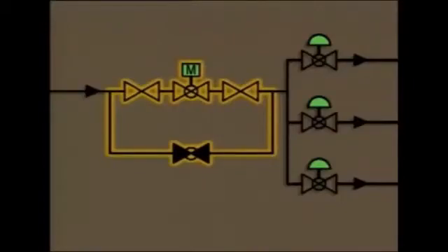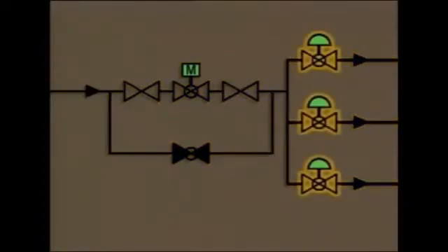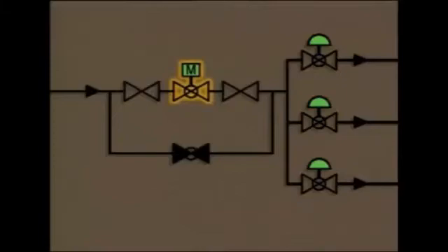This equipment controls flow to 3 separate piping branches. Each one has a pneumatically actuated globe valve to control flow through the branch. This symbol represents a motor-actuated globe valve. An automatic control system operates the actuator to regulate flow through the valve and the supply line. These symbols represent 2 gate valves that function as isolation valves. It's a manually operated globe valve.